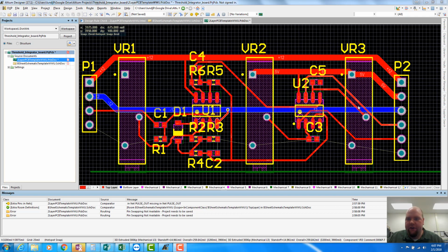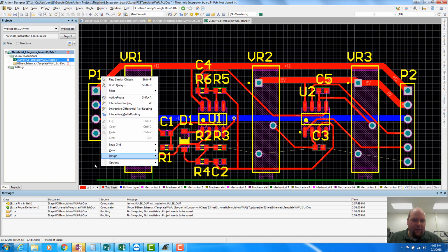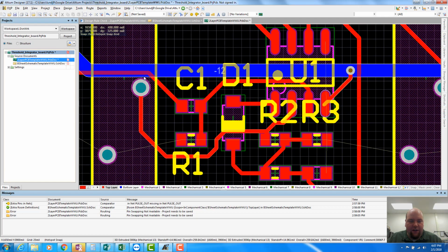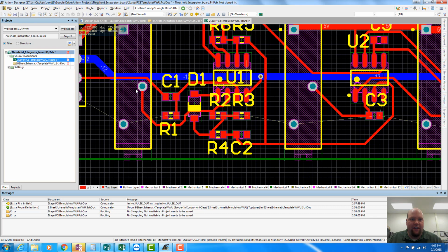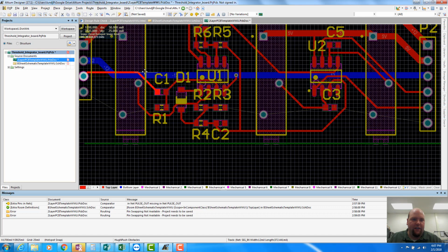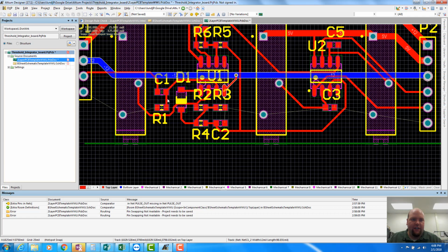Okay, so we're trying to get that ground in place. I'm looking at where my grounds are, and I'm not too worried about them, with the exception of one. I think it might be easy. So this guy, there might be an issue getting ground to him through here. The good thing is a couple of these are pretty easy to just move around some routes right now to help get a ground signal in there without it creating a big hassle. So we're going to give that guy some space so that ground can work its way in there with a nice fat trace.